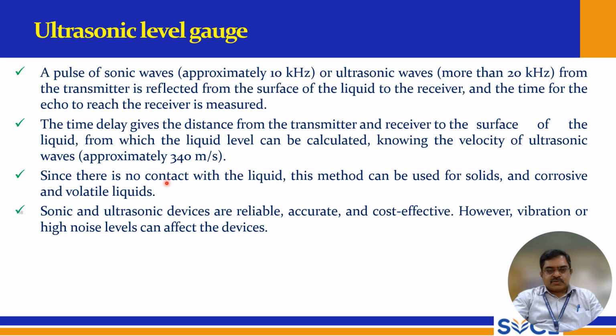Since there is no contact with the liquid, this method can be used for solids and for corrosive and volatile liquids also. Sonic and ultrasonic devices are reliable, accurate, and cost effective. However, vibration or high noise levels can affect the devices. So that is another drawback.